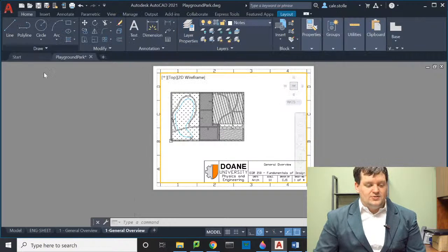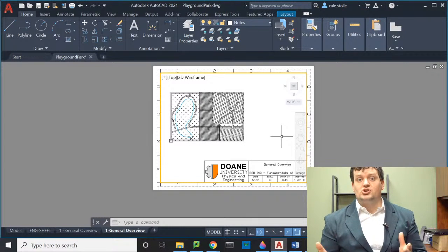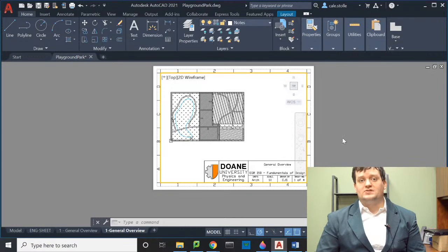And then when I close, what you'll notice is it's a very clean view that only shows certain layers. The whole reason why we drew in certain layers on our drawing was for this reason, because you can shut off the layers inside of your viewports. And it gives you the ability to really see what's going on in a much cleaner fashion.